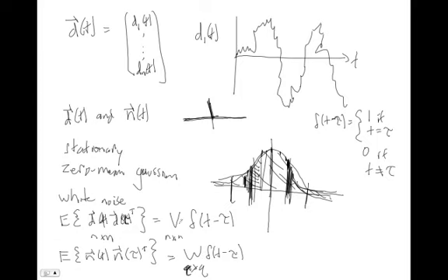These matrices V and W basically encapsulate the size of our disturbance and the size of our noise. And when I say size, it's more in this variance way. If this is the process for any one of our disturbances or noises, you can think of the value in V or W as essentially this value here. So how big is the spread of this thing?